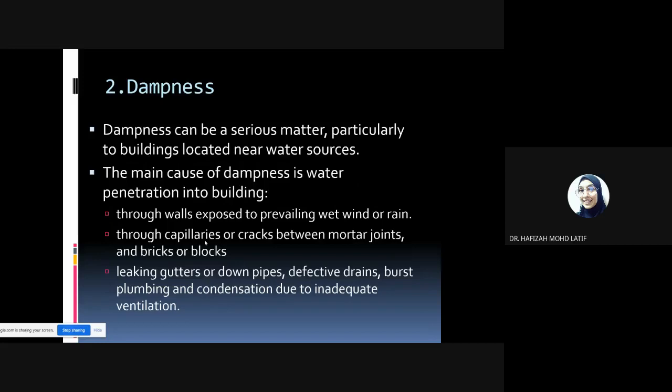We thought that in that room the piping had burst, meaning the pipe broke inside the floor. When you have a burst or leaking pipe, you can have a wet slab. But the services are not in the slab. The water pipeline and air conditioning were all suspended underneath because the slab is a precast slab, so there are no services inside the precast slab.